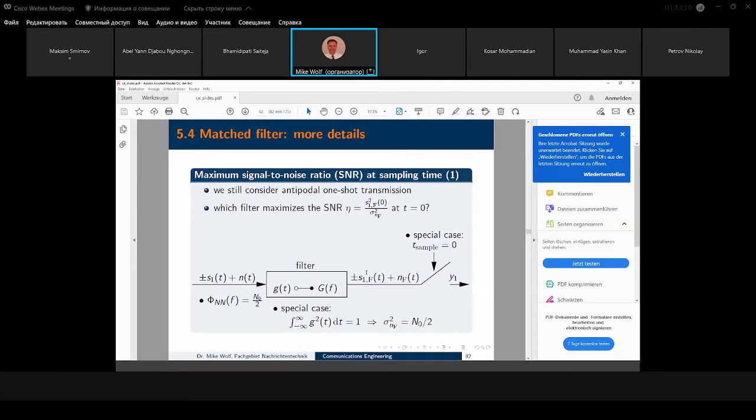Why do I do this? Because, first, this derivation is simpler. Second, later we will see we can use signals for modulation which are longer than this modulation interval. And in our modeling, we could even say these signals have an infinite duration. So these basis functions, maybe these basis functions are sinc pulses in the time domain, so they have infinite length.